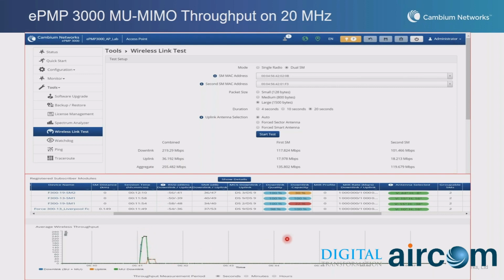What you are seeing here, the antenna, is the smart antenna that does beamforming. Beamforming works by narrowing the beam from your traditional 90-degree sector to a smaller angle, which makes it run away from the source of interference and increases your link budget.